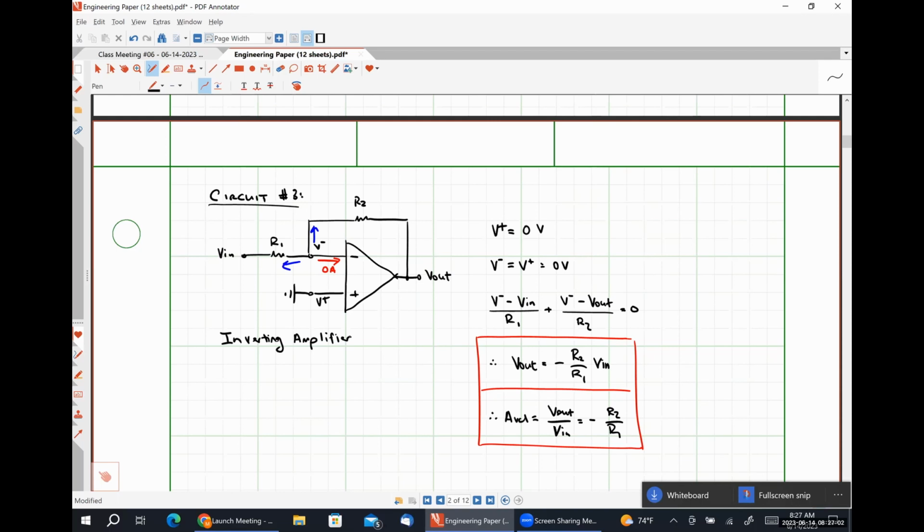So in a lot of applications, the sign of our output signal doesn't matter one bit, particularly in simple audio signal amplifiers and things like that. Our output signal being 180 degrees out of phase really doesn't have any significant impact on the behavior of the audio amplifier, because it's just going to be some time varying signal that's driving a speaker. So it doesn't matter. That 180 degree phase shift really means nothing. But we can both amplify and attenuate with this thing.